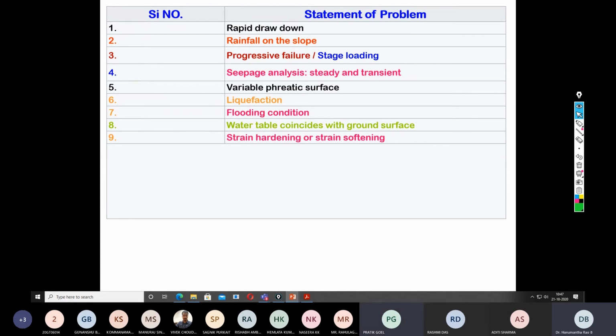For example, seepage is an imminent phenomenon. By no means can you avoid the seepage. But when the seepage exceeds a certain value, then there is a danger. We cannot totally eliminate the seepage. Depending upon the conditions there, we have to take the measures. You need to assume all these conditions and envisage what happens if the seepage exceeds this value.